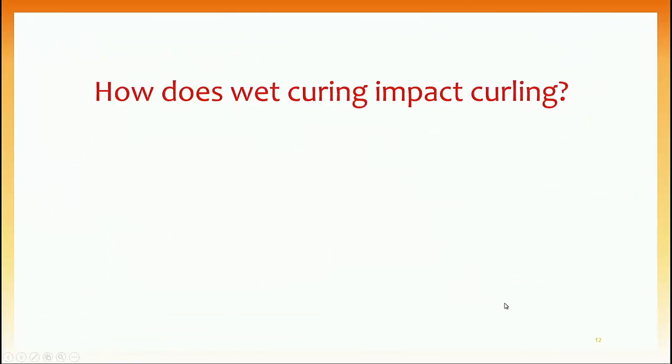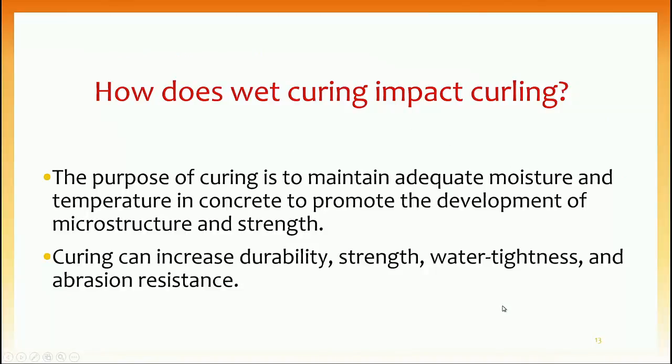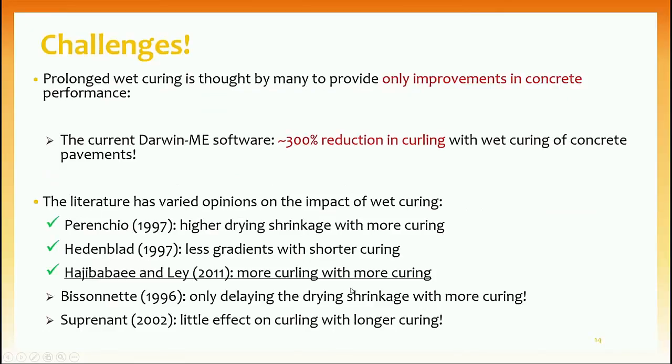How does wet curing impact curling? As you know, the purpose of curing is to maintain moisture and temperature in the concrete that can help develop a tighter microstructure. Therefore, curing can increase the durability, strength, water tightness and abrasion resistance. But there are some challenges. Prolonged wet curing is thought by many people to provide only improvements, such as what I've shown in the previous slide.